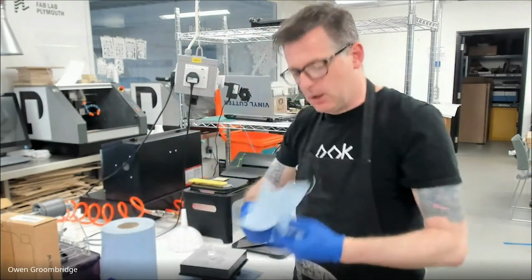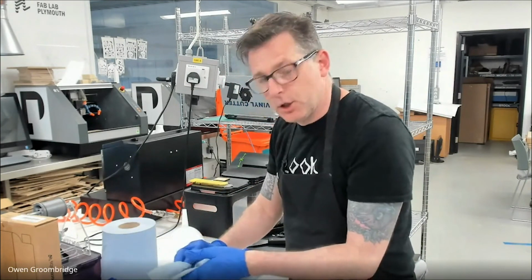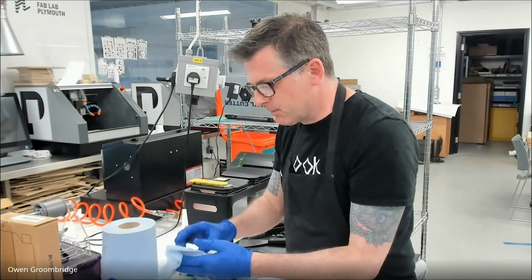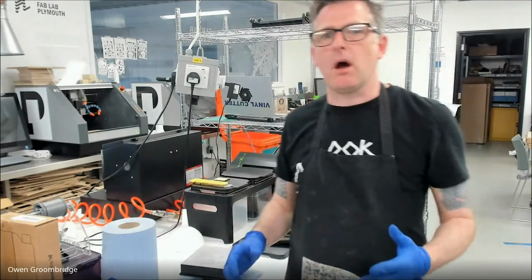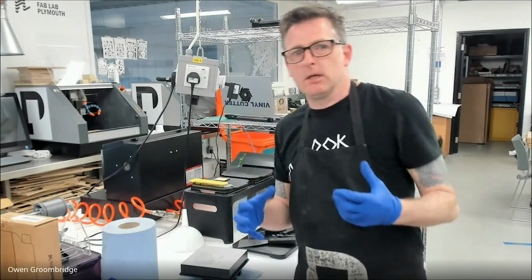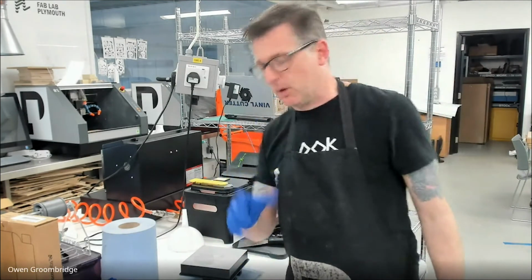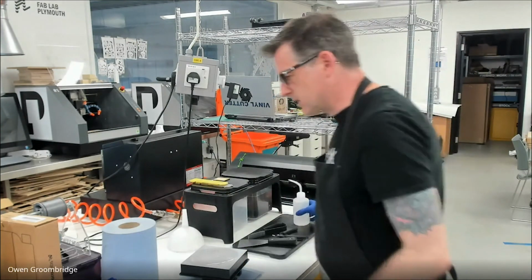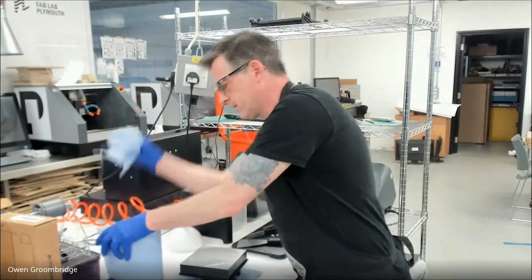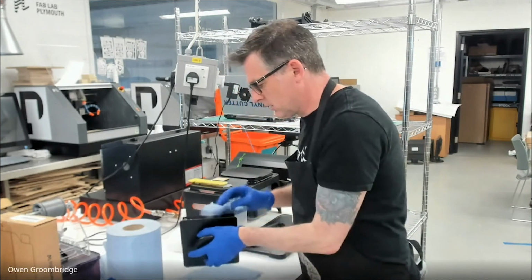because generally speaking, you do not want alcohol on these objects when you cure them. The main reason is that what I tend to find is that it doesn't cure properly. They can end up being sticky, and sometimes curing is not enough. It takes a long time to get rid of that residual stickiness of prints, particularly large ones. Now this is ready to be reused again, almost. I'm just going to give it a squirt of alcohol and wipe that down. There we go.